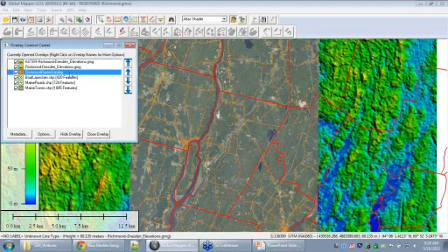On top of that, I have created a map catalog file, and a map catalog is a Global Mapper format that allows us basically to store a collection of raster tiles. So what I have here is a map catalog of about 12 different tiles at about 1 meter resolution. This is derived from the U.S. NAIP imagery sets. So each of those three types of data that I just mentioned, the NED data, the ASTER data, and the NAIP imagery specific to the U.S. here, those are all online data sources.